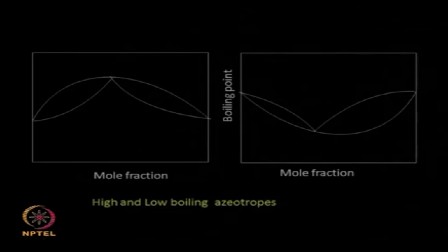You sometimes change the pressure condition so that the azeotrope may go, or you sometimes add a third component so that it breaks the azeotrope, and nowadays we are resorting to even membrane type of situations where we can break azeotropes, because membranes do not work based on vapor pressure, membranes just work based on either size or molecular weight, solubility and so on actually.